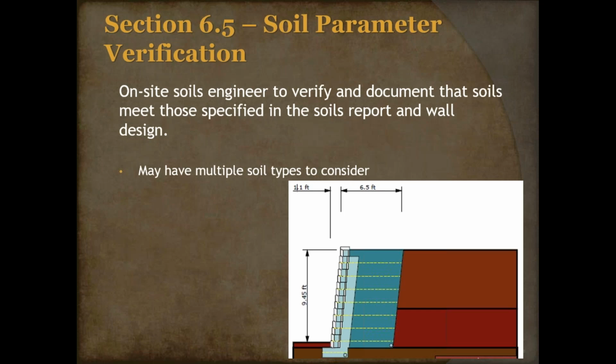And so understanding the scope of work is important, but then that gets into educating, and where Allen Block comes in, we're trying to educate the contractor, making sure they realize not every soil is what they call brown. We don't care about the color per se. We want to know what type of material it is. So that's important to classify the soil.